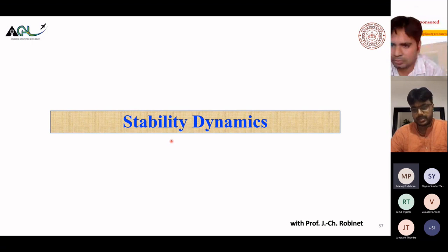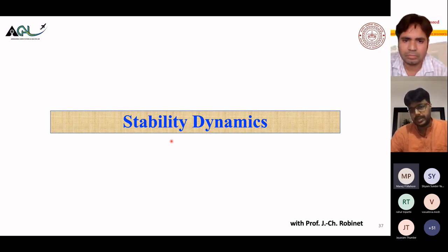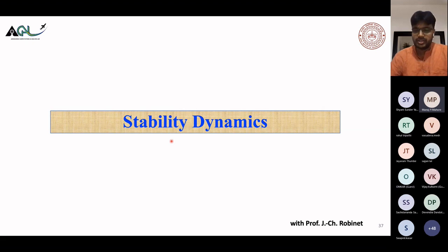I'll go through one last aspect, which is again the application of a tool, linear stability analysis. People normally perform stability analysis on very simple canonical flows, for example, on a flat plate or a lid-driven cavity or open cavity kind of thing, because these are very, very expensive.